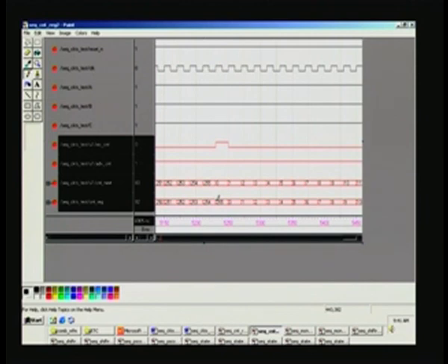When it is 255, this reset counter, which is a combination circuit of sensing counter reg equal to 255, which happens right here, immediately goes high, being a combination circuit, and remains so as long as it is 255. It is 255 throughout, and once this is done, this will make the counter 0 in the following positive edge of the clock. That is what you see here, and thereafter it keeps on rolling around, and it increments from 0 onwards, because it is being reset here.